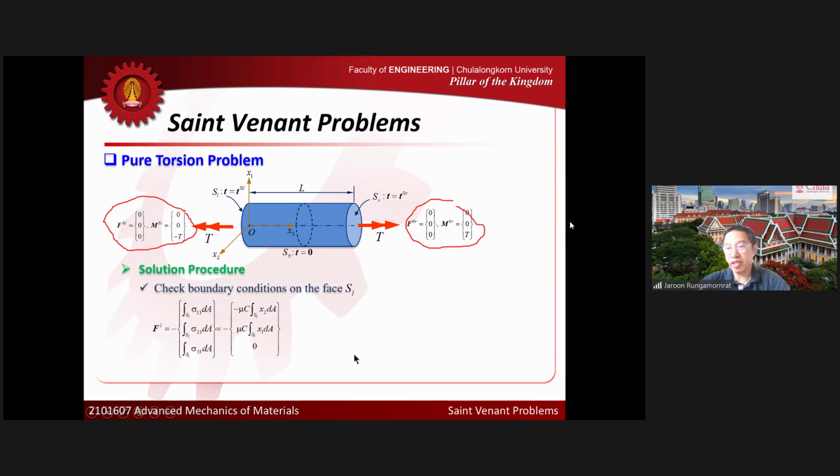Okay, so it's quite clear here that the integral that we have there vanishes, right? Because the origin that I showed there is at the centroid of the cross section, and for this particular case it's at the center of the circle. So the integral here should be 0, right? Because of the definition of the centroid, that term disappears and that term disappears.